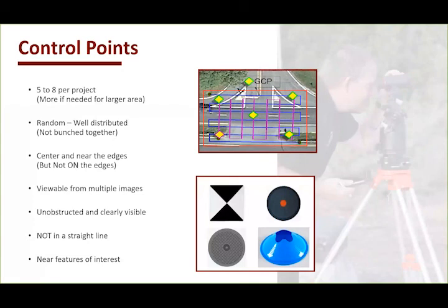Because that's the interesting thing. You can in fact use photographs that are not geotagged. GPS data is not really needed to create the 3D image. The geotags that come from the craft help with the scaling and the orientation, and then if you're using GPS control points, it's actually giving you a good position relative to maybe your state coordinate system, maybe that you're tying it into a real-world location.